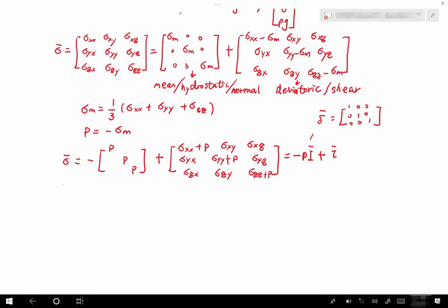So by extending this simple thing that we learned at high school, we can get another thing, that is tau is proportional to, so the deviatoric stress, the shear stress between the two plates is proportional to the gradient of velocity. That's u over the distance between the two plates. And the proportionality constant, we use mu. That's the viscosity.